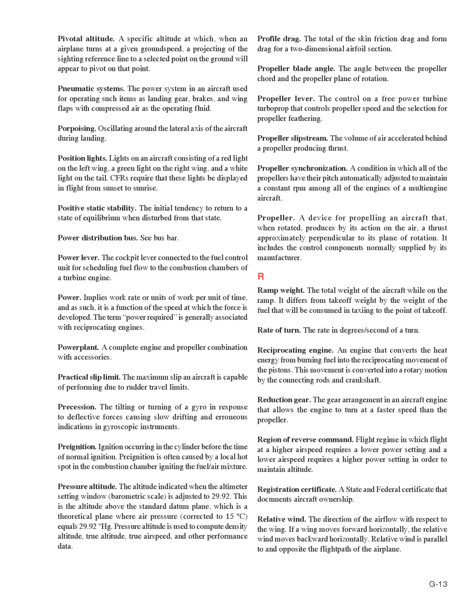A condition in which all of the propellers have their pitch automatically adjusted to maintain a constant RPM among all of the engines of a multi-engine aircraft. Propeller. A device for propelling an aircraft that, when rotated, produces by its action on the air a thrust approximately perpendicular to its plane of rotation. It includes the control components normally supplied by its manufacturer.